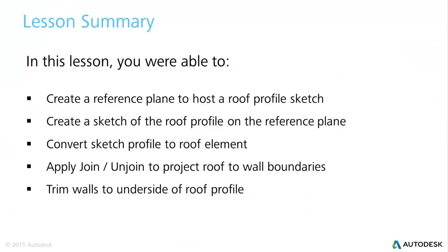Let's review the learning objectives for video 1. In this lesson, you were able to create a reference plane to act as design aids for constructing a roof profile sketch. Then we created an open profile sketch of the roof that we were seeking on that reference plane. We then converted the sketch to a 3D roof element and then used cleanup techniques using the join unjoin tool to project the roof to wall boundaries. And then the last task was to project the walls to the underneath side of the roof envelope. With that, let's take a look at Autodesk resources that are available to you.